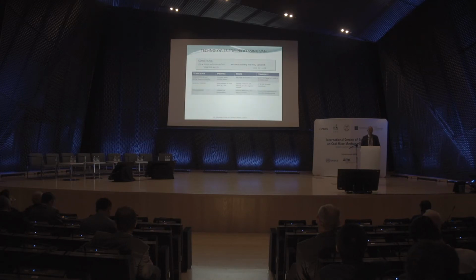There have been trials on lean gas turbines, and they have typically managed to come down very far, but below 2-3% is difficult. And also the volume is an issue. The volume of a ventilation shaft is so large, so you would need a lot of turbines to handle that.